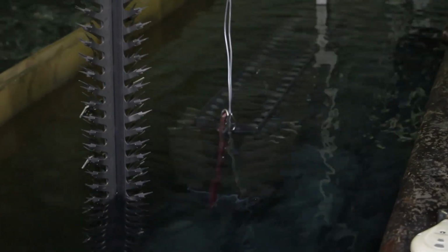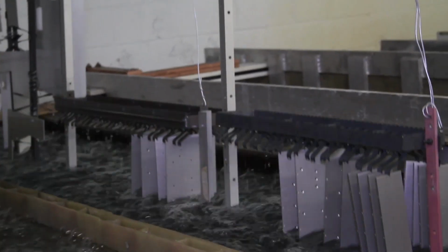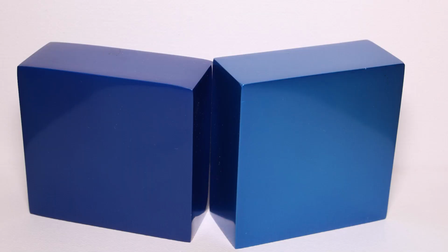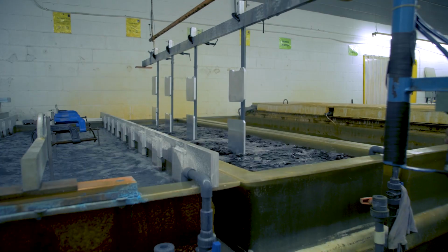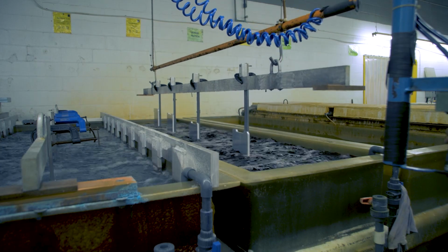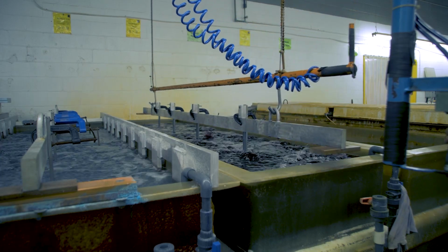Anodizing is an electrochemical process wherein aluminum is placed in a liquid bath with an electric current flowing through it. This produces a chemical reaction that thickens the oxide layer on the surface of the aluminum, which in turn increases the aluminum's durability while also allowing for electrical conductivity. One caution with anodizing: this finish is completed off-site by a third-party supplier, so there will be additional lead time and cost.